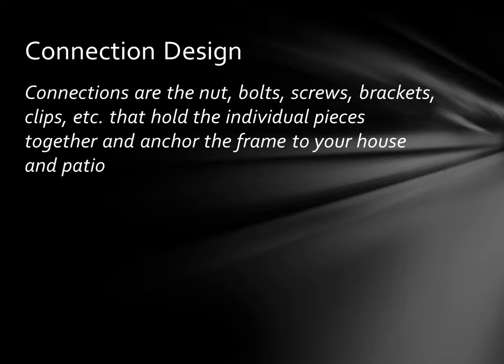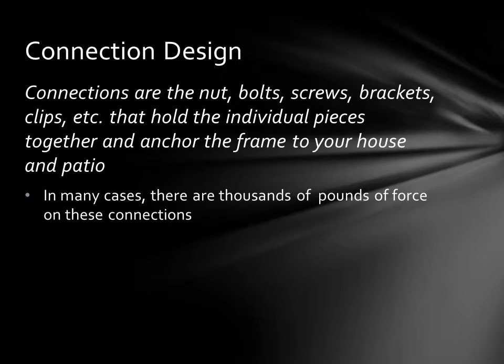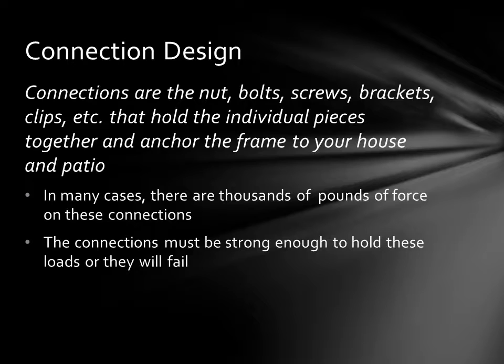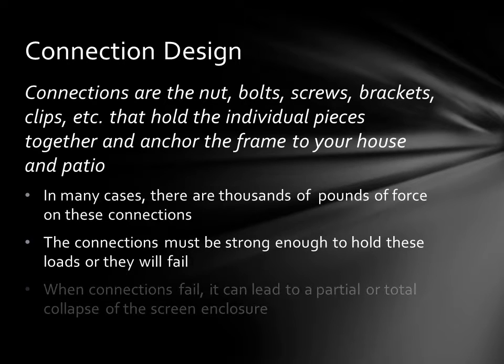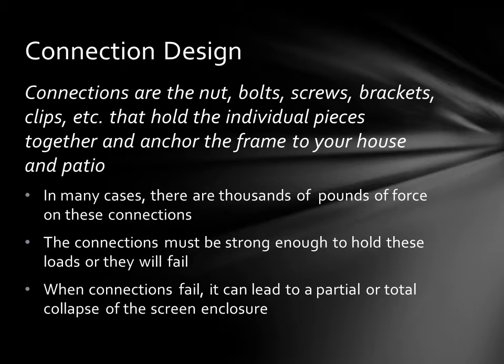Connections are the nuts, bolts, screws, and other miscellaneous hardware that hold the individual pieces of the frame together and anchor it to the house and patio. In many cases, these connections are subjected to thousands of pounds of force, and the connections must be strong enough to hold these loads or they'll fail, which can lead to partial or total collapse of the screen enclosure.